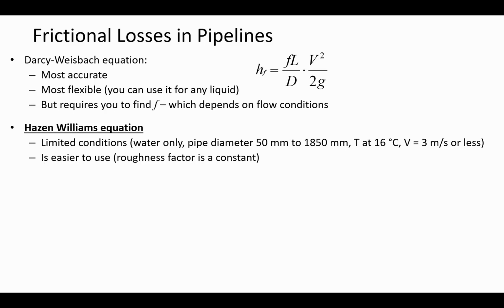And so we do need to know the viscosity of the water when we calculate the f value, because viscosity is one of the terms that goes into Reynolds number. And whether it's the Swamee-Jain equation or the Colebrook equation or whether it's a Moody diagram, we have to know the kinematic viscosity in order to calculate f. So Darcy-Weisbach actually is sensitive to changes in temperature, whereas Hazen-Williams, they just calibrated it for 16 Celsius. There's no sensitivity or adjustments for temperature.